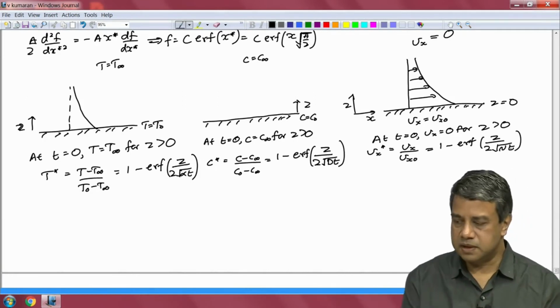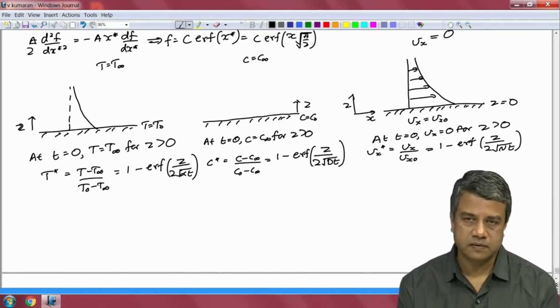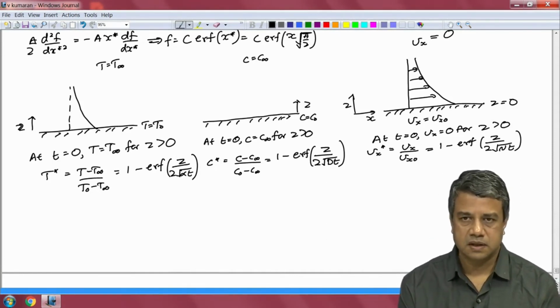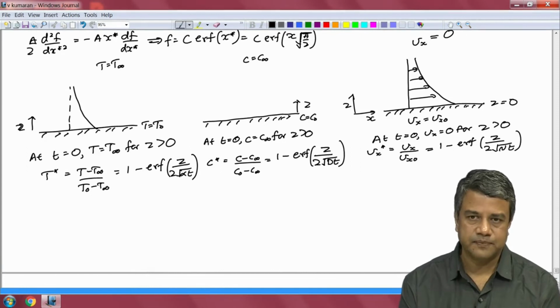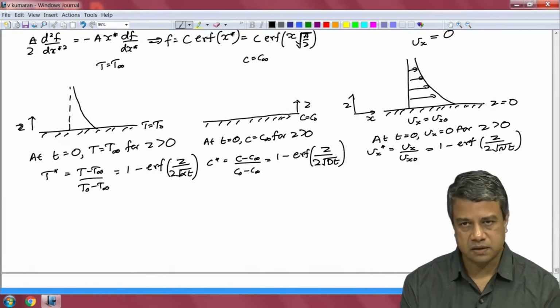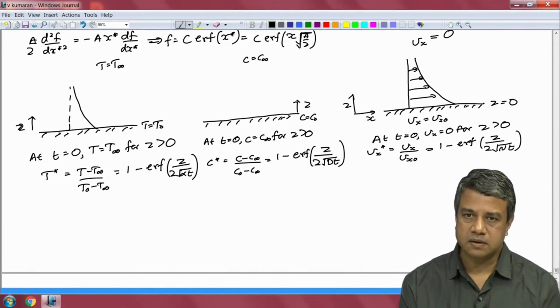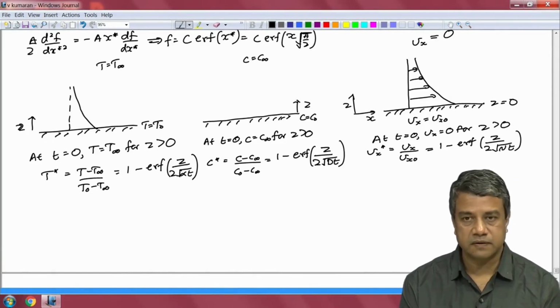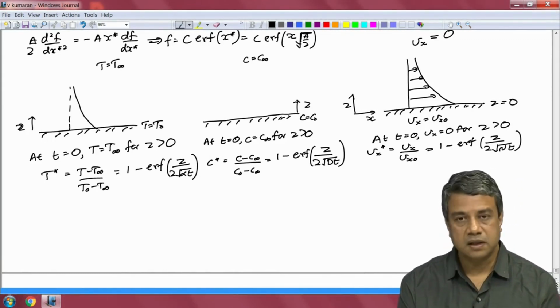Substitute the momentum diffusion coefficient for the thermal diffusion coefficient and the velocity for the temperature, and the equations are the same. The momentum conservation equation is obtained by substituting velocity for temperature in the energy conservation equation and substituting kinematic viscosity, or momentum diffusivity, for the thermal diffusivity in the energy balance equation. So, the solution is also the same.